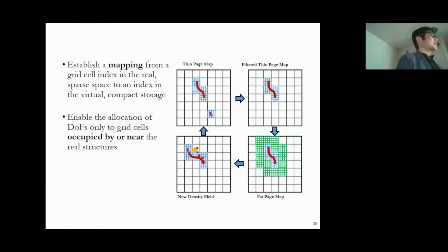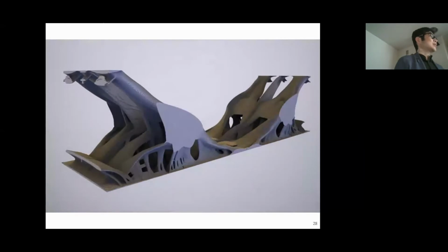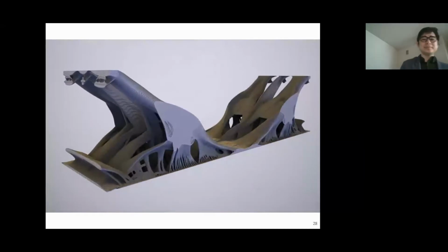And we can dynamically allocate our computation by looking up this TLB table and by looking at where the materials are in each evolution iteration. So that means we have created a hierarchical sparse populated grid, and we can use this grid to optimize different types of structures that exist in a very large physical space, but actually exhibiting sparse and hierarchical geometric structures.